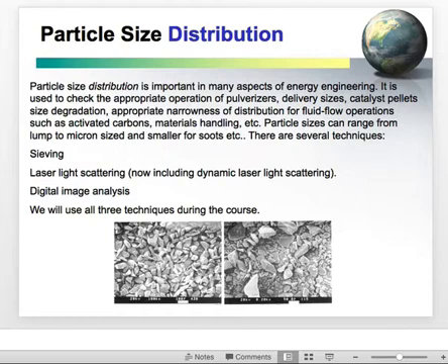So this is some coal particles under the SEM. You can see that with wet sieving I obtained a relatively narrow particle size distribution, and that many of the particles are the same relative size. There is still a range. Obviously, they're not spherical particles, and often we assume spherical particles, so this shows that that's clearly an error. If I do dry sieving, you can see I get a much broader distribution.